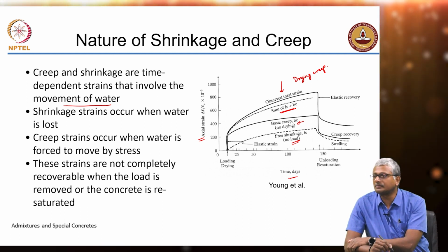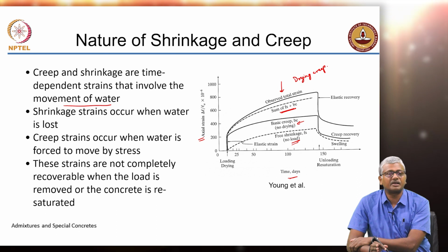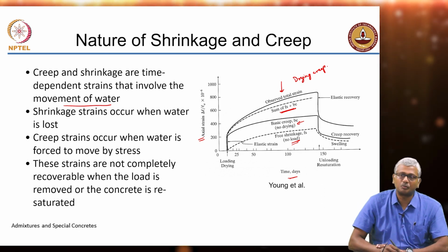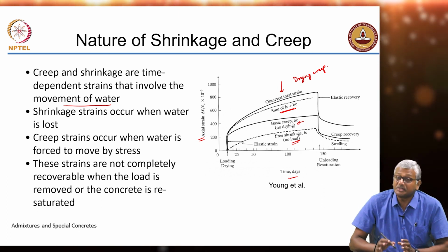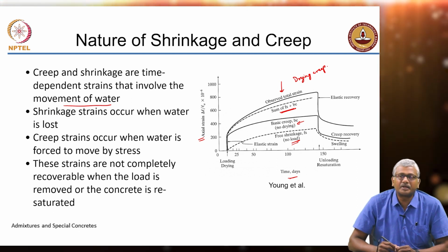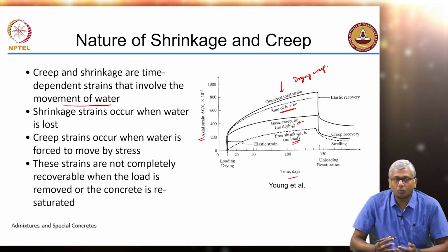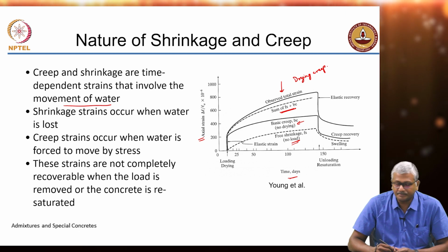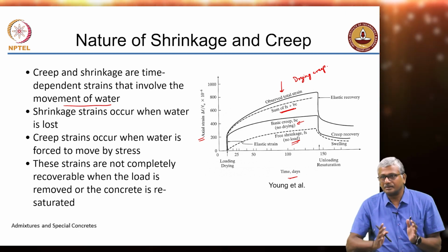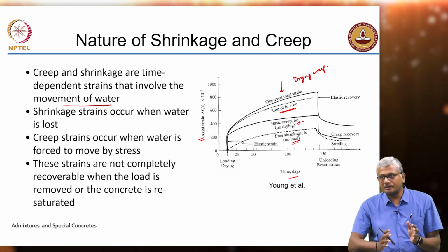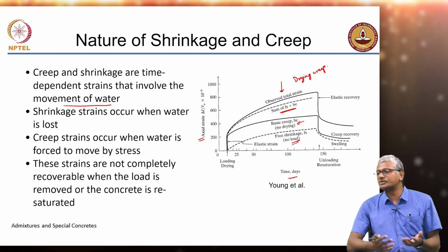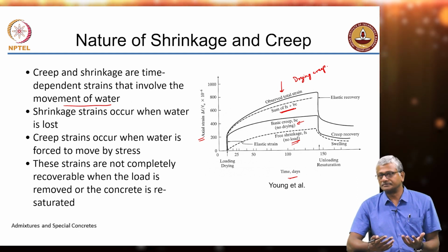It is no longer the creep coefficients that are prescribed in IS 456, they are not permitted to be used anymore. You need to start measuring, and that is where it becomes very critical to understand what is contributing to the overall deformation. Okay. But needless to say, the movement happens because of the presence of water inside.